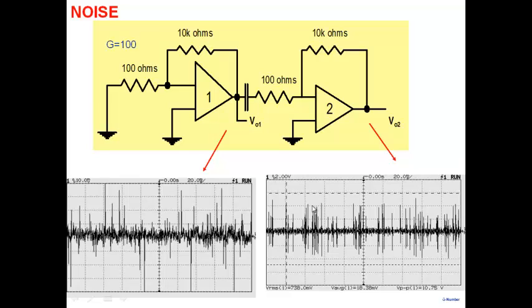When you connect to an oscilloscope and you are seeing it after several minutes, all those initial conditions die down. All transients die down after about 3 tau, or so, of the RC. So this is not initial condition. This is steady state. And this is what you see here. Now, where is it coming from?